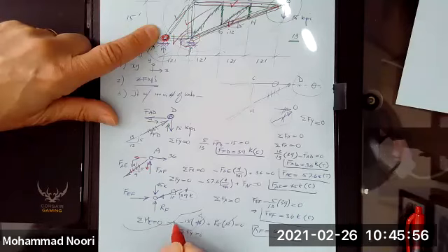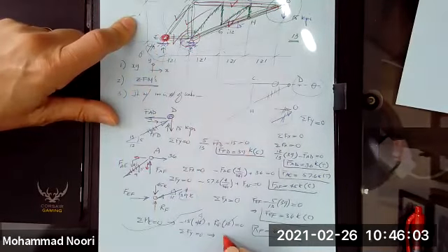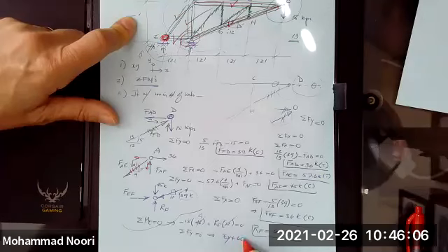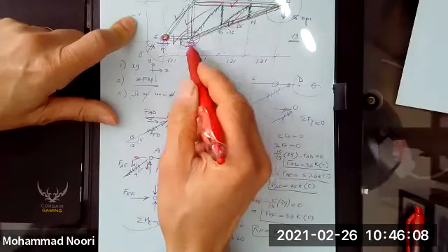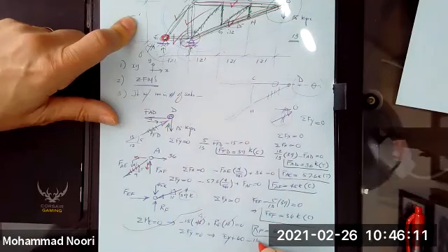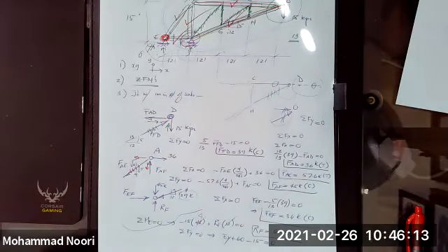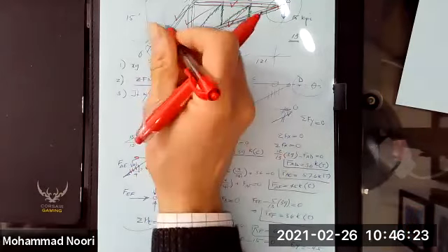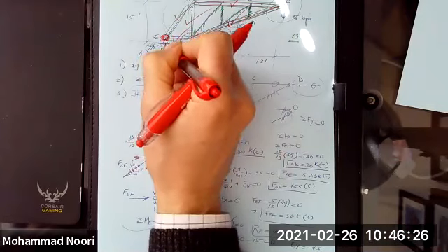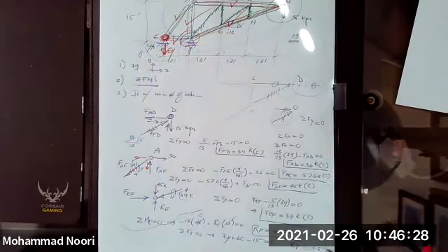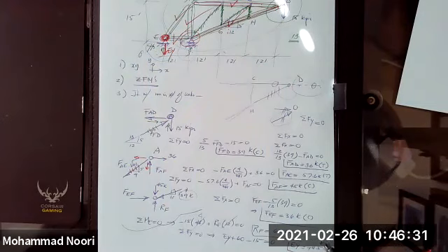So I use this one, that one, equal to 0. What does that give me? That gives me EY plus 60, minus 15 equal to 0. That means EY comes out to be negative 45. That is, the assumed direction here is wrong. So this is EY, 45 kips.